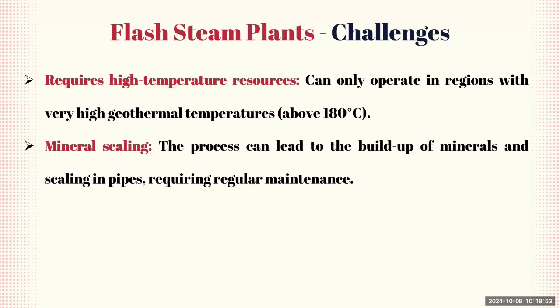Also, another issue is mineral scaling, where the process of flashing steam can lead to the buildup of minerals inside pipes, known as scaling. So this requires regular maintenance to ensure that the system runs efficiently and avoids any blockages.